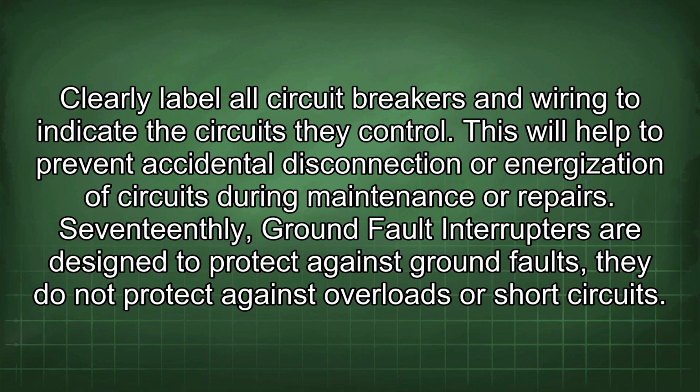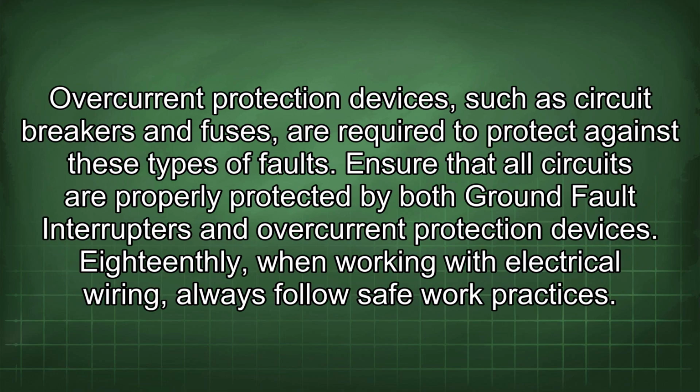17th, ground fault interrupters are designed to protect against ground faults. They do not protect against overloads or short circuits. However, overcurrent protection devices, such as circuit breakers and fuses, are required to protect against these types of faults. Ensure that all circuits are properly protected by both ground fault interrupters and overcurrent protection devices. 18th, when working with electrical wiring, always follow safe work practices.